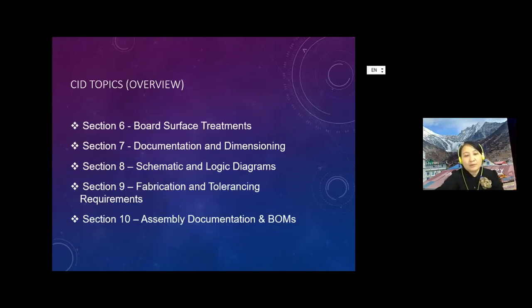And then we also have surface treatment, as in, do you use HASL lead-free or do you use ENIG? Because ENIG can be expensive, right? And can you replace it? Is there a cheaper version? Now, of course, we talk about documentation and all the basic stuff. So this is a basic entry level to ensure that you know all the terminology and have something to demonstrate that you already know all these terms.